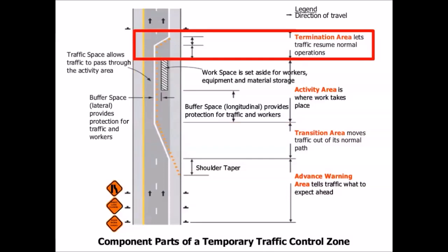I mentioned keeping everything as simple as possible, right? Give them the easiest way of interpreting when your sites end. Downstream tapers, again, would be one of those things that's considered optional according to the CA MUTCD. But if it takes setting up 4 cones to let them know, hey, now it's safe to merge back into that lane, it's easy to set up 4 cones, guys. So do it so people understand, hey, from this point on, it's okay to merge back into that lane.